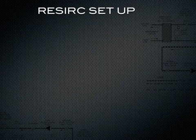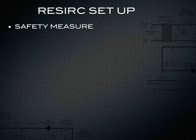An important reason to have a recirc setup for your process as opposed to a once-through is that the recirc setup can act as a safety measure for your refrigeration system. On a once-through, you're going to have 1 loop with 1 pump, so everything's going to be intertwined with that chiller evaporator. If your process goes down or if there's a restriction of flow rate, your refrigeration system potentially could shut down.